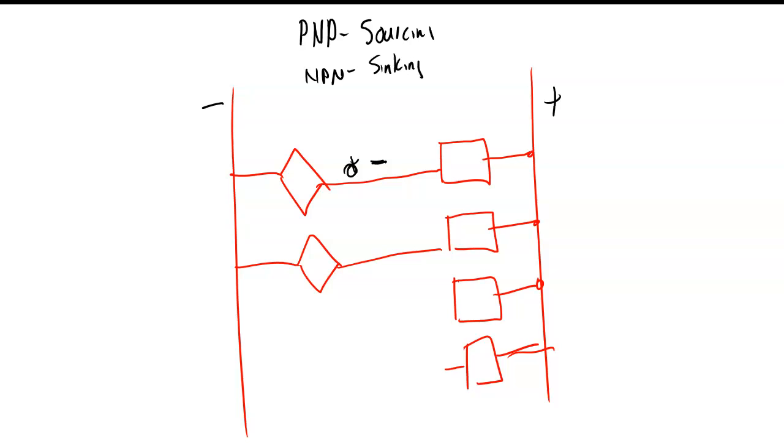So this is why it's very important when you deal with these PLCs to know what type of input they use. And that's some of the things when you buy them, that's what you specify. And most of these companies, everyone that I've ever seen, gives you all that information for free. So if you get into a company and it's got a Siemens PLC up there, and you look at the number and search for the operator's manual on that PLC, you'll be able to get it, and it'll tell you right off the bat whether the inputs are sinking or sourcing.